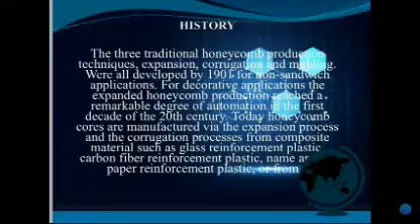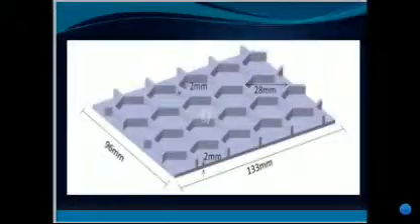Today, honeycomb cores are manufactured via the expansion process and corrugation process from composite materials such as glass fiber reinforced plastic, carbon fiber reinforced plastic, paper reinforced plastic, etc.